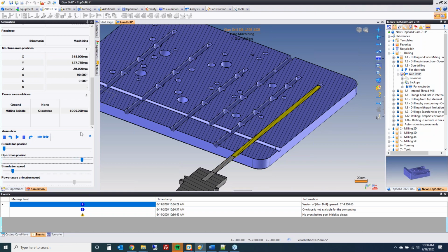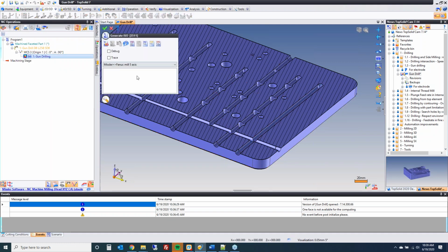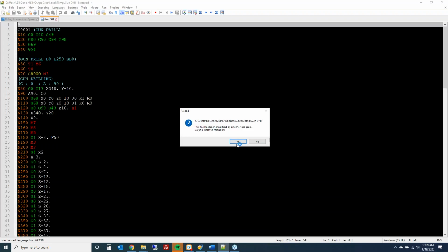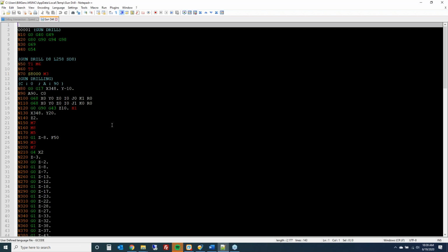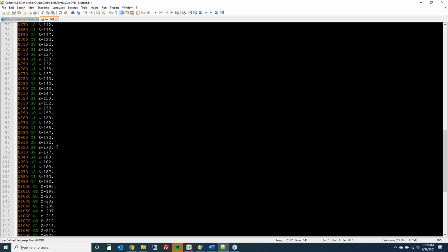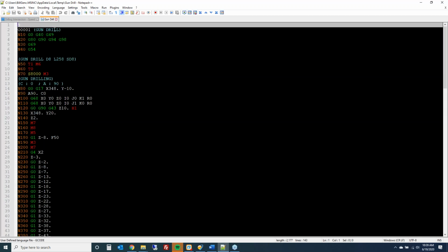And then here, once it gets to depth, notice counterclockwise, 4,000 RPM. Okay, and again, I think we should look at G-code because G-code really helps to understand what's going on. So let's go ahead and take a look. And here we go. Now, because it's broken up and whatnot, of course, it's a longhand cycle, but you can see it's doing everything we told it to do in very simplistic form. So now you have full control over deep hole drilling, however you want to control it, without having to create any type of custom cycles. So a great new improvement.